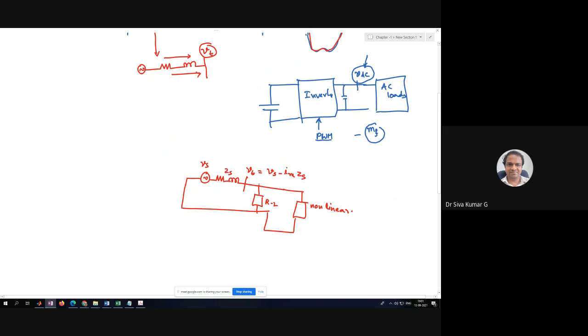My point is, the terminal voltage has the fundamental component as well as the fifth harmonic component, or third harmonic component. In that case, what happens to this RL load? Then I_RL becomes Vt by Z, which is of fundamental value. I'm just given about Z only.